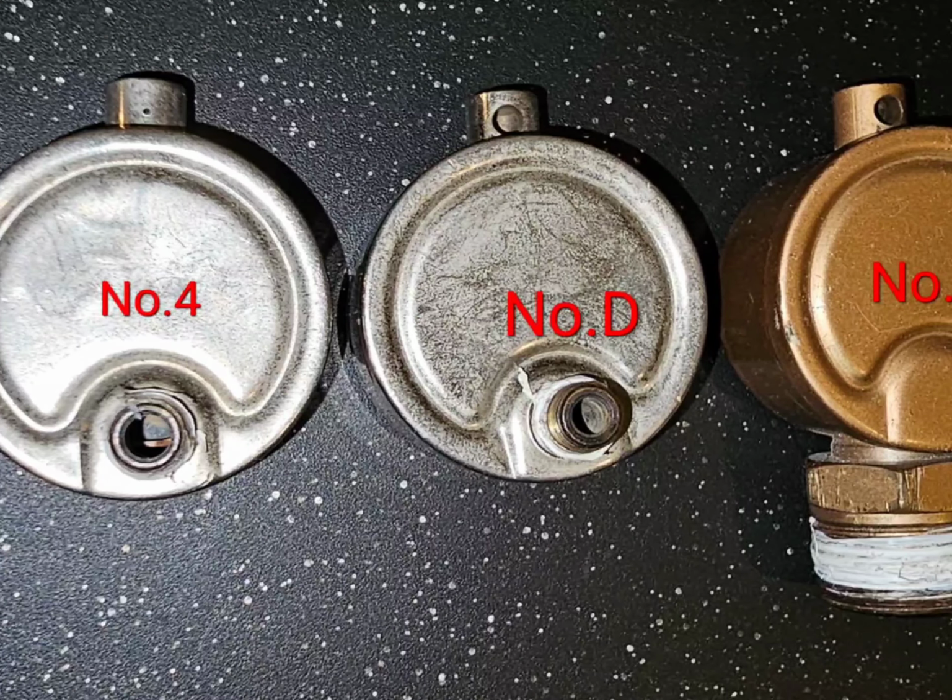So here we have a Gordon's number 1. And this is what you should find on a steam main. Let me just go ahead and say this much. Under no circumstances should you be using, and this is a straight air vent, so you would figure this would be excellent for a convector. Well, you might be able to do that if it's a cast iron convector. You have a better shot.